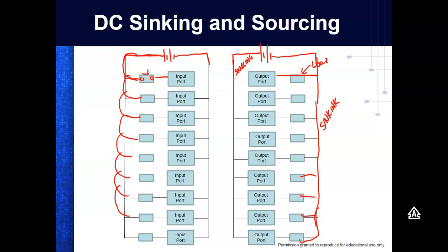First of all, you've got a DC power supply anyway, right? So you already have that. Plus, 24 volts DC is the standard voltage now for PLCs. But if you get into older situations, a lot of your control devices were AC devices. That means odds are, if you get into older applications, you're going to have AC inputs or AC outputs. In your applications, you'll probably have DC inputs, and the outputs depend. There's still a lot of DC stuff out there.